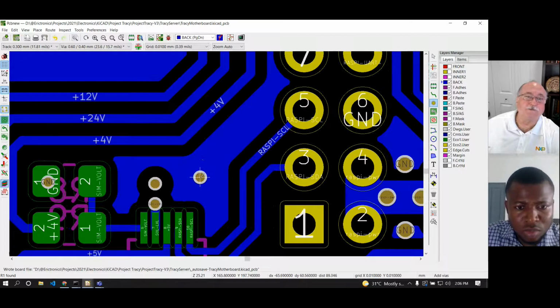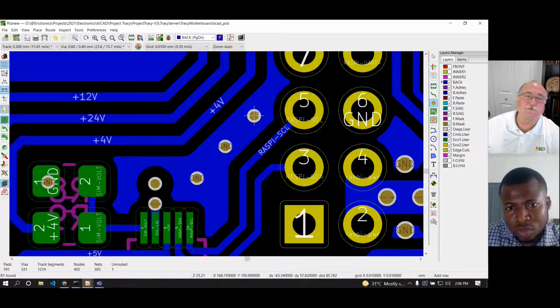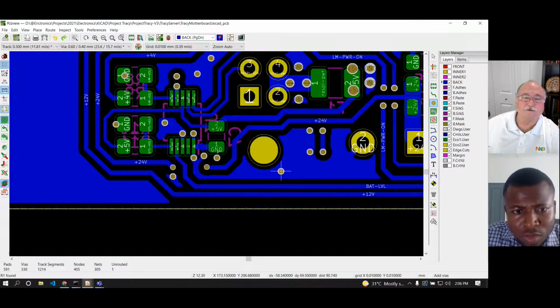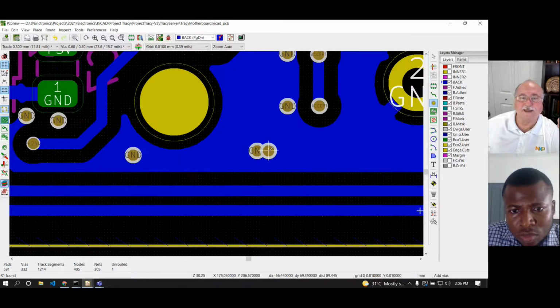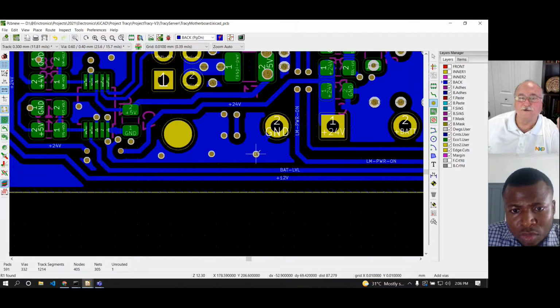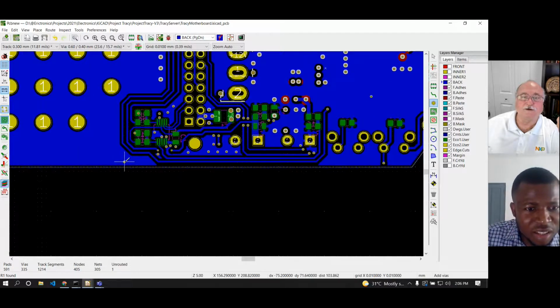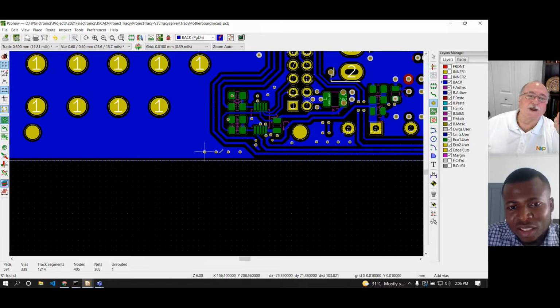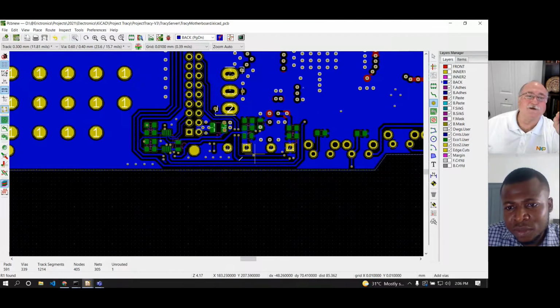On the bottom, let's see, that one you want to put up towards there. Those are nice. And then on the bottom, there's a piece of copper coming across along the bottom here. Wherever you can along the edges of the flood, you drop some ground vias to kind of bound it. And then one above that one, and then along there. Some people do stitching vias around the edges. It doesn't hurt anything, but it's not needed. But like what I just did with one of my boards, wherever there's flood like this, I'll wrap vias around the edges of the flood.